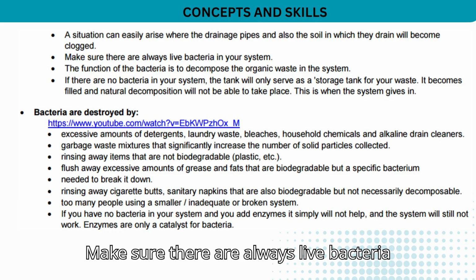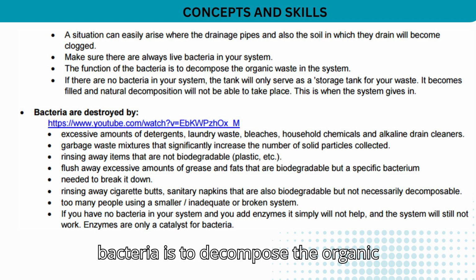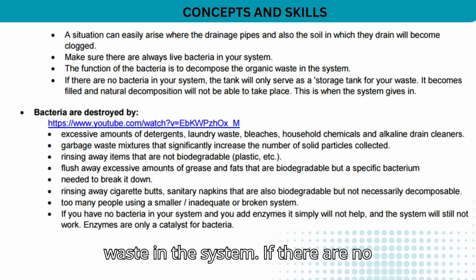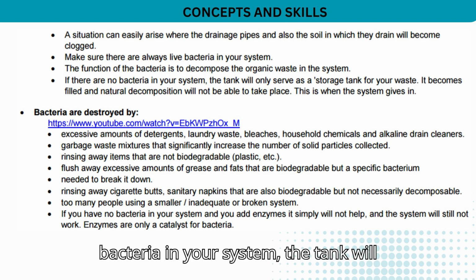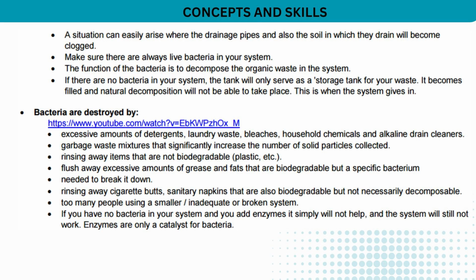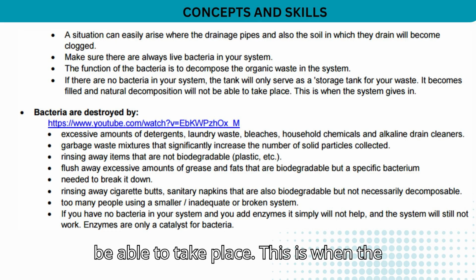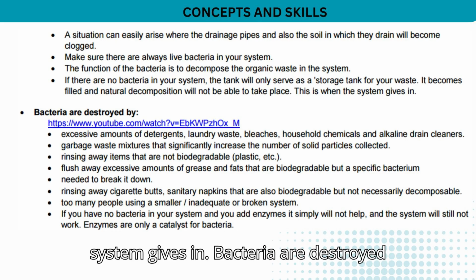Make sure there are always live bacteria in your system. The function of the bacteria is to decompose the organic waste in the system. If there are no bacteria in your system, the tank will only serve as a storage tank for your waste. It becomes filled and natural decomposition will not be able to take place. This is when the system gives in.